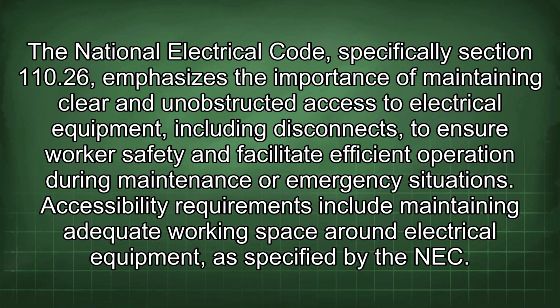The National Electrical Code, specifically Section 110.26, emphasizes the importance of maintaining clear and unobstructed access to electrical equipment, including disconnects, to ensure worker safety and facilitate efficient operation during maintenance or emergency situations.